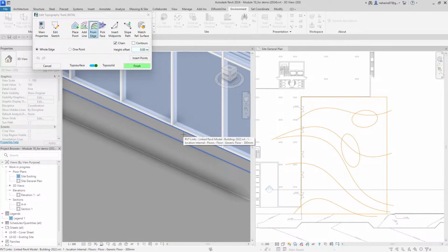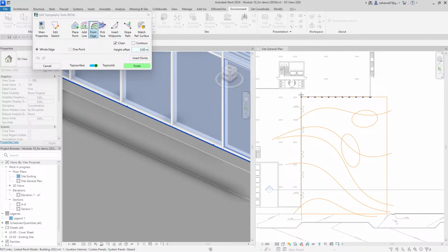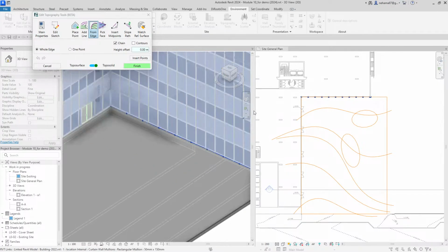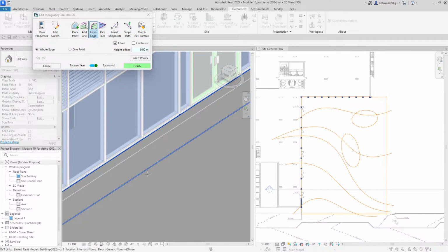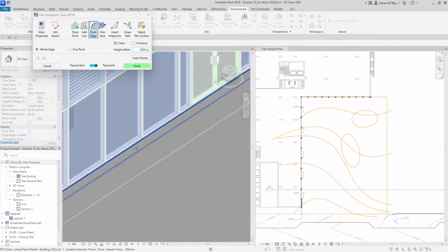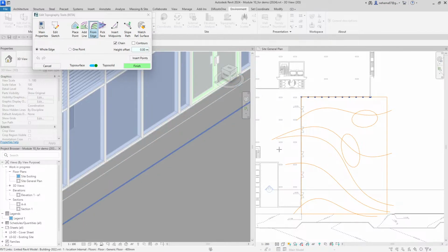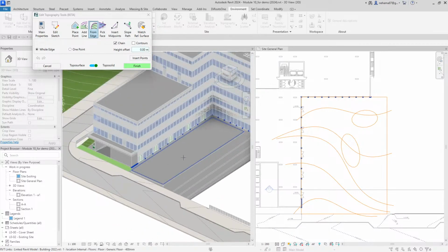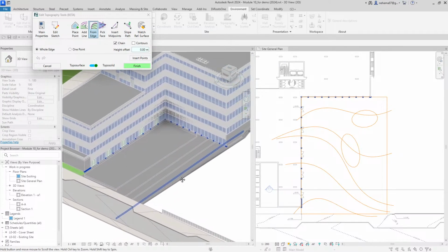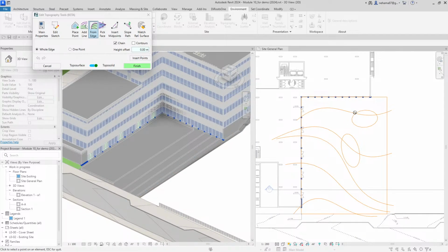take a look at my 2D view. As I click, you can already see the elevation points. Let's do the same thing under the doorways over here. By the way, if I want to deselect, I just have to click on it again, and you can see that the points are disappearing. So let's select again. Now don't be confused. I know it looks an awful lot like a Toposurface, but that's just the graphics that we chose to use because it's very convenient. So now if I like where my points are placed, I'm just going to go with Insert Points.